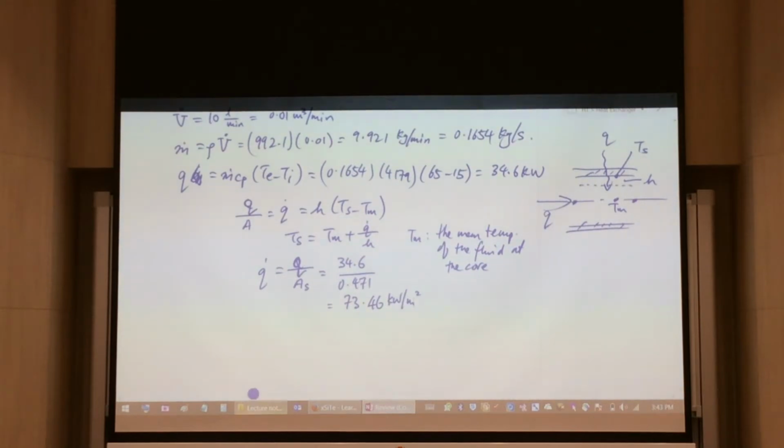So next thing is to find out what is my average velocity. So I'm going to represent the average velocity in the following way. Capital V, subscript AVG for my average velocity. And I need this because I'm going to use it to figure out if the flow is turbulent or laminar. So this is a topic of convection, so you need that. So this equals V dot divided by Ac. That's how you're going to find out what is your average velocity.